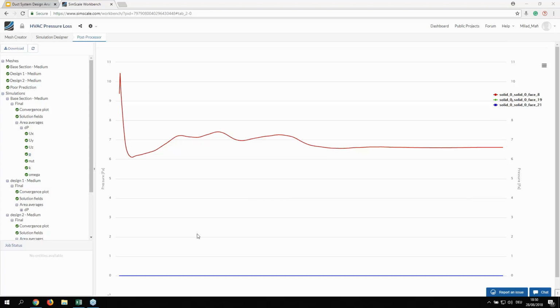Then Walid wants to know how complex duct geometries should be modeled, for example, the flow through each volume control damper and sound attenuators. His basic question is whether, using this simulation, he can determine the opening angles of the blades of each volume control damper, if they are modeled well enough with 3D geometries.